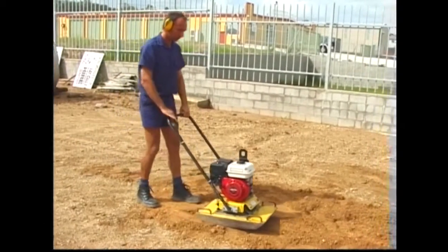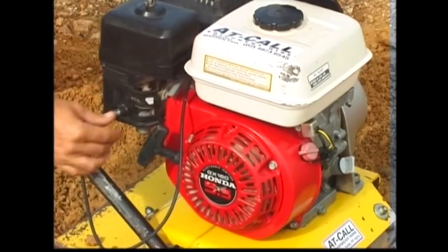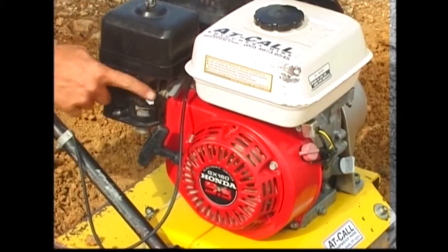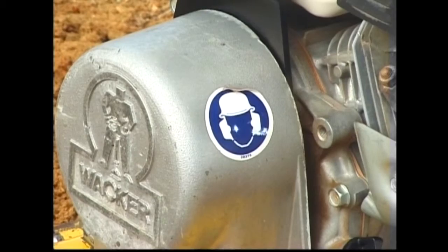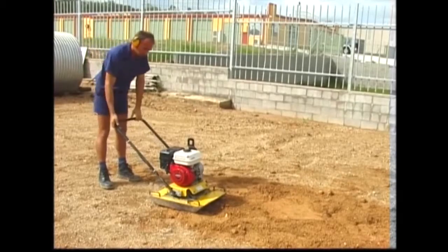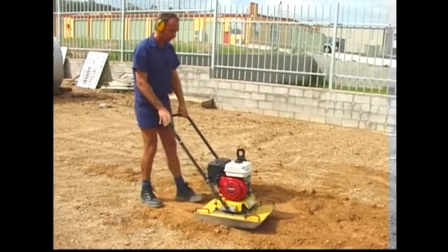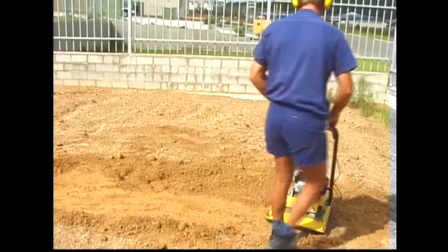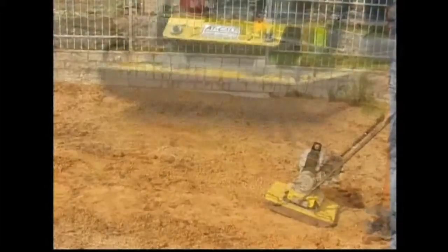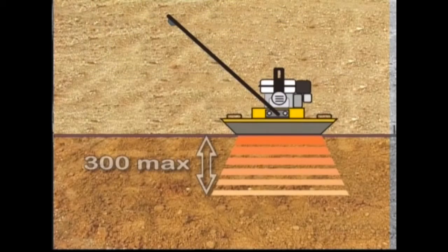When compacting is required over a wider surface, a plate compactor is used. Applications include compacting bedding under slabs and preparing surfaces for pavers. Plate compactors are effective to a depth of 300 millimeters.